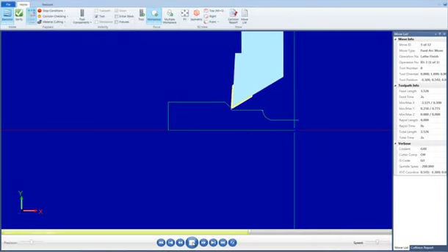We will now post the file. Posting refers to a process where the toolpaths in Mastercam are converted to a format that can be understood by the machine's control, specifically the G-codes. In most cases, every machine will require its own post-processor, customized to produce code formatted to meet the machine's exact requirements. Ensure all of the operations are selected from the Operations Manager.